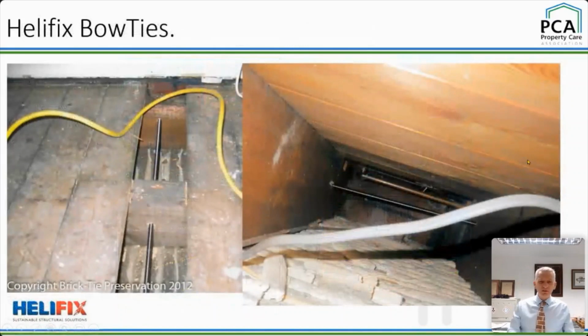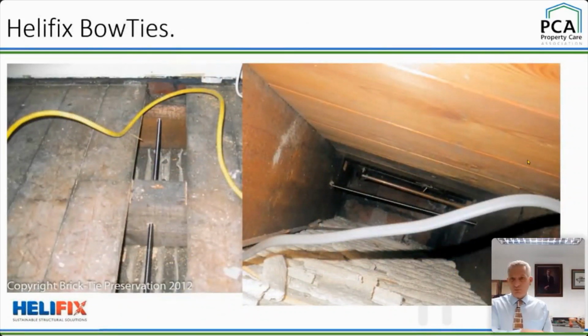So, move on. I mentioned helifixed bow ties, but that was just because that's what we used on that job. Ordinary straps done properly can work very well. Not plugged and screwed into the wall, because plastic creeps under load, and you should never load a plastic plug and screw fixing coaxially. It should only ever carry shear loads. But the manufacturer will say, oh yeah, I use these all the time.